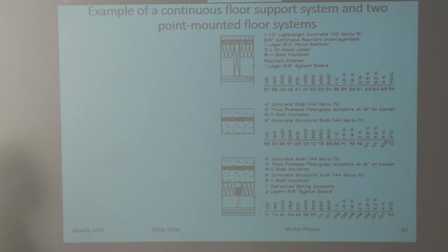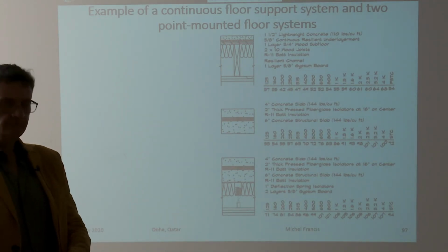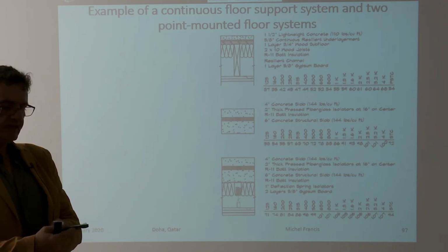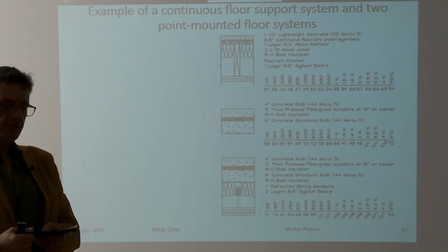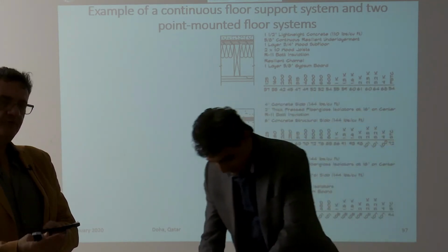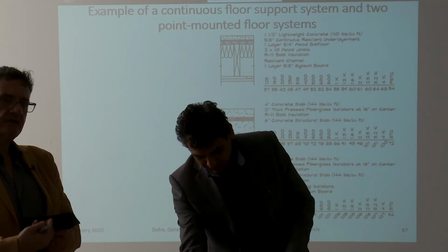One surface of this floating floor will be in contact with the wet concrete, right, sir? The above surface, yes, he is right. With this floating floor, the grooves underneath will be open and it will sit on the dry part. The top one, definitely you have to screed on top of it. On top of that mat there is a plastic coating, so the wet will not go inside. The critical point is the edge. Some concrete might flow here, pick this up and go underneath.